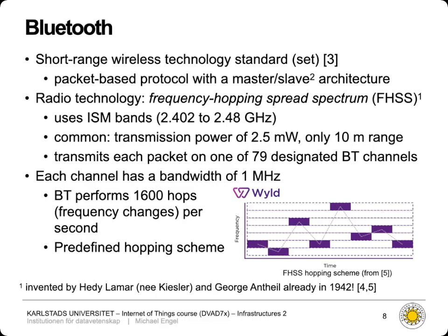So Bluetooth is interesting because it tries to avoid conflicts in this very crowded 2.4 gigahertz band. It uses what's called frequency hopping spread spectrum. So two communication partners, when they want to set up a communication, do not just agree on a fixed frequency range within that ISM band, so a subset of a frequency band, but they actually switch the frequencies relatively quickly, and they have a joint algorithm to switch frequencies. So even if there is interference between, for example, a Wi-Fi connection and a Bluetooth connection, this only lasts for a very short time because Bluetooth changes the frequency it's operating on very soon after, in the range of milliseconds. This is very nice to use, but of course it requires agreement, so sender and receiver have to use the same frequency hopping scheme in order to find each other again.